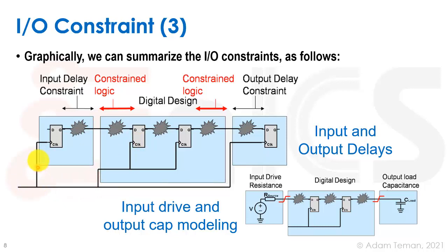And that will be added basically to this capture path in this modeled thing. But we don't actually add any propagation delay to this piece of the net, and therefore we cause useful skew that we didn't really mean to plan for. We didn't mean to cause it. The way that the Cadence tools right now take care of this is that they take an average of all the propagation delays of the clock tree into the design and put a negative number on where the actual rise time of this clock net is after clock tree synthesis.